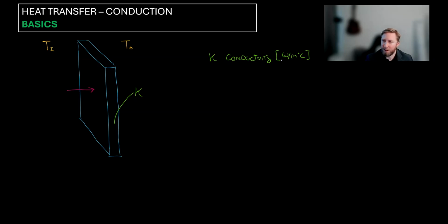And the units of conductivity also explain what it's all about. It describes how much energy or heat can move through a meter thickness of this material for a difference in temperature of some amount. So that's the conductivity, and it is important for determining the thermal properties of the wall.